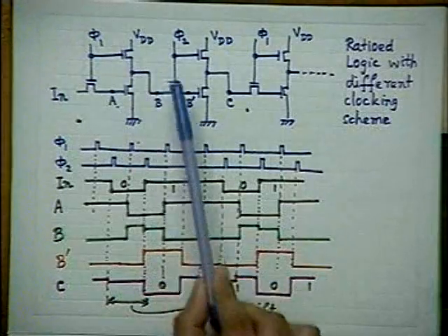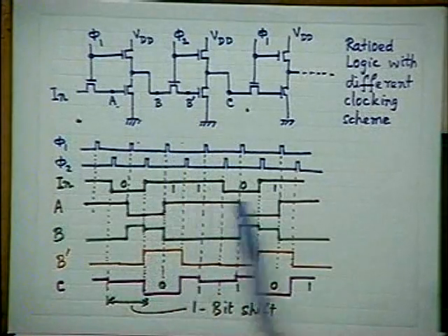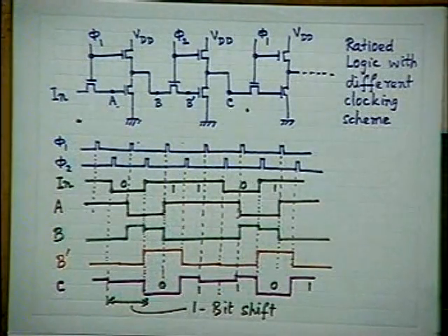But if you remember something I did in connection with the transient analysis of the MOS inverter, the same analysis is applicable to determine, if you like, the similar kind of equations. The same way we advanced, we did the analysis exactly. All those methods are applicable here to determine what is the minimum clock rate needed for the proper functioning of these devices. Similarly, you can also find out what is the minimum pulse duration needed for the proper functioning of this circuit. This is one thing.